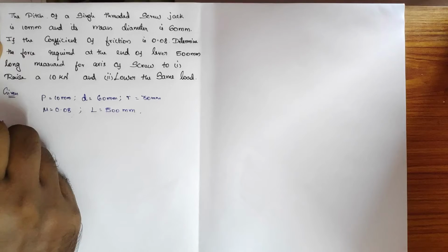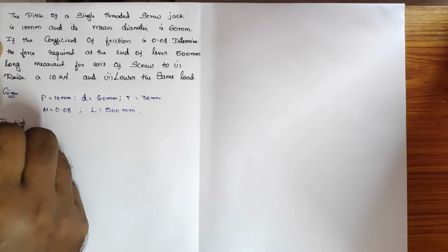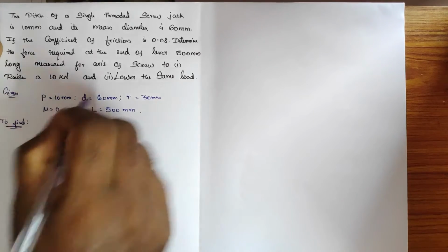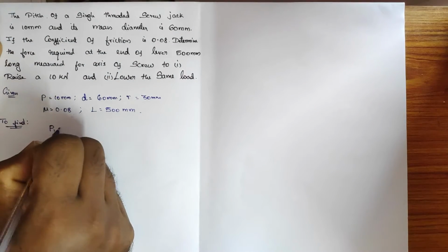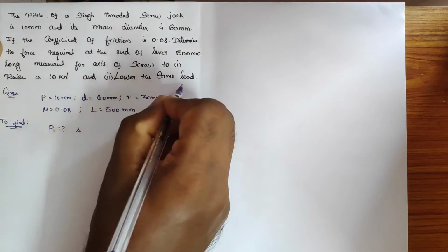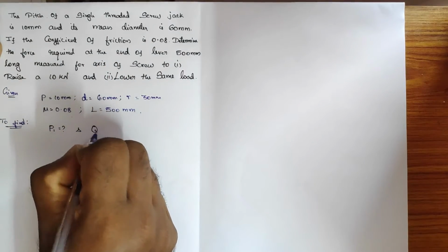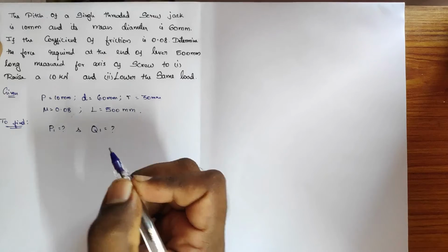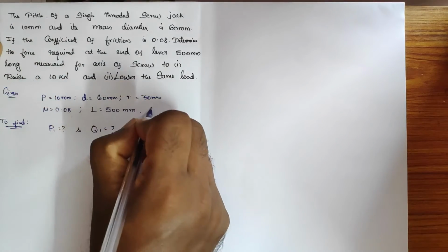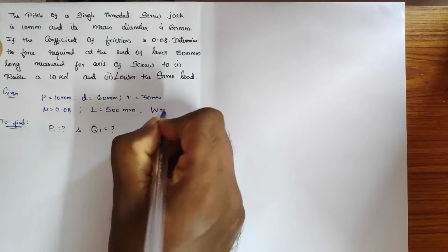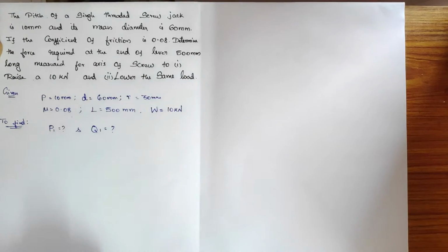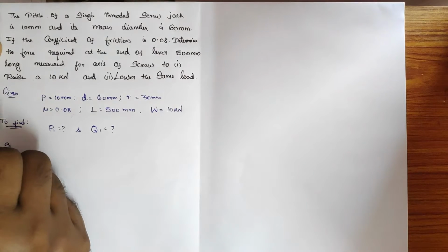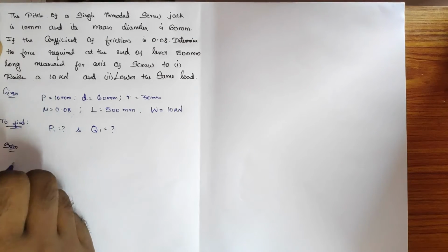Okay, to find the effort required to raise, so P1 we need to find, and to lower the same load, so Q1 we need to find out. So here the weight of the load on the screw head is given, which is 10 kilonewton. Okay, solution. I am just going to find out first the effort required